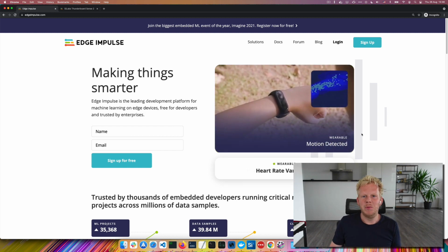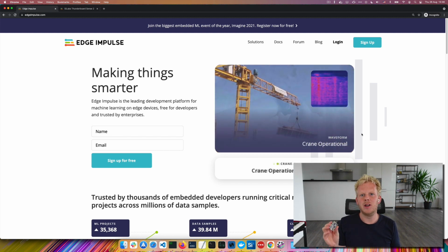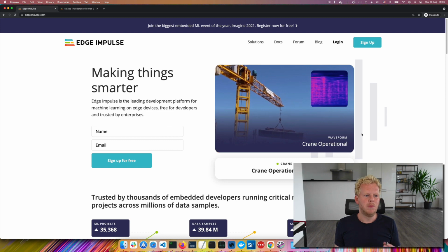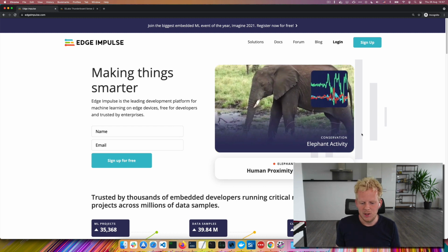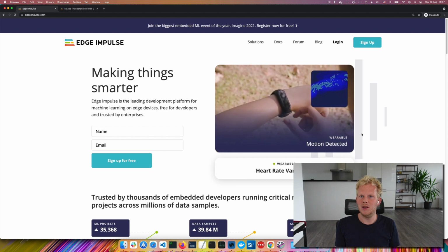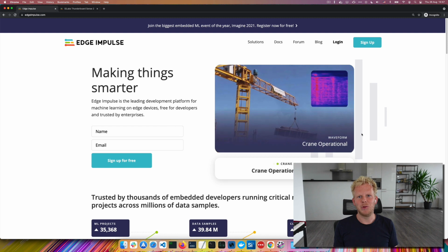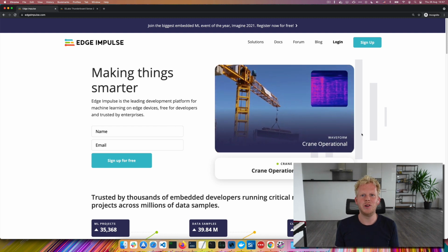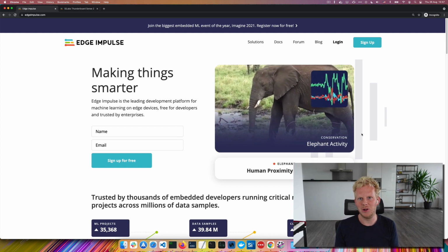To do that, we have built a custom firmware, and that firmware has binding code to all the sensors on the dev board, plus it has a serial protocol that allows us to capture that data straight from the device. So this gives you access to the raw data as we receive it from the device, so nothing downsampled or at lower resolution. In addition, we do some stuff like cryptographic signing of this data, so you know which device generated that. Not as important as we're just doing a workshop here, but becomes much more important once you deploy this at scale.